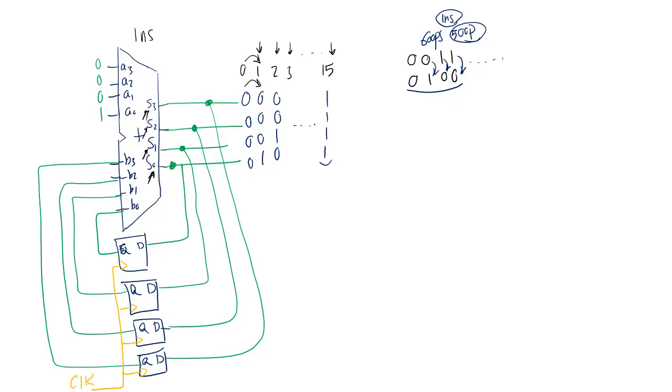So now at the positive edge of the clock signal, I take one sample and only one sample of the output and copy it to the second input of the adder, right? At the positive edge of the clock. And that way, using this clock, I can make sure that I have very good control on the timing of my counter, so I can count slow, fast, at whatever pace I like based on the frequency of my clock. Okay, so now this is really a counter.